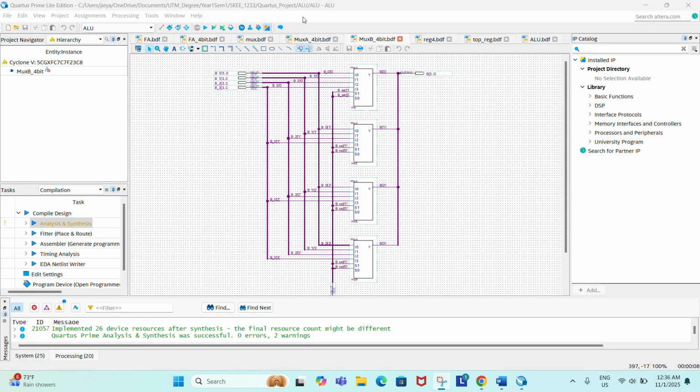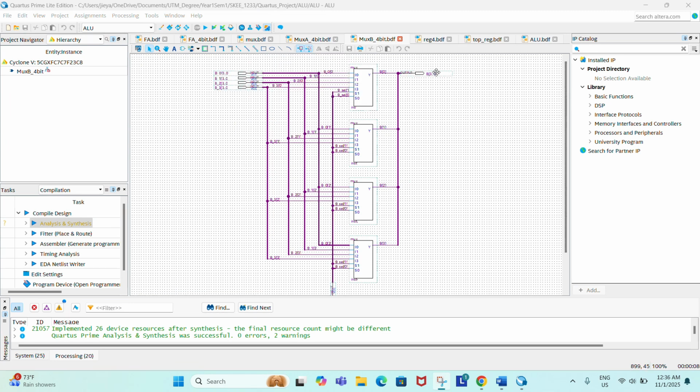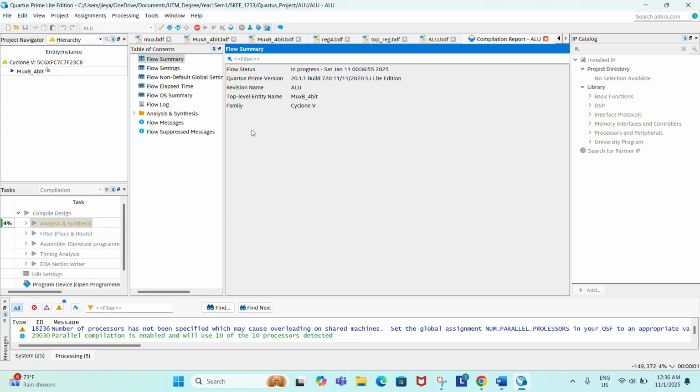This shows that the design for the 4-bit 4-to-1 multiplexer for A is correct. We will also use the 1-bit 4-to-1 multiplexer symbol to create the 4-bit 4-to-1 multiplexer for B. The circuit will have 4 4-bit inputs, 1 2-bit input, and 1 4-bit output, and is connected by using 4 symbols of the 1-bit multiplexer and bus wiring. Now let's run the waveform simulation.